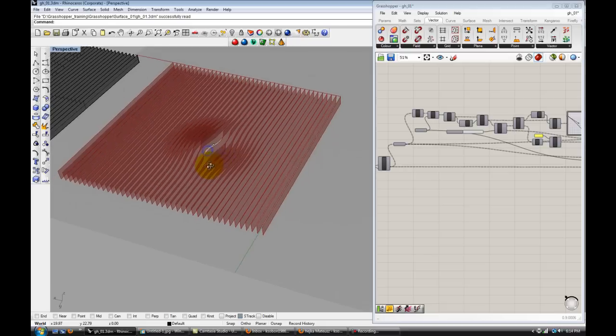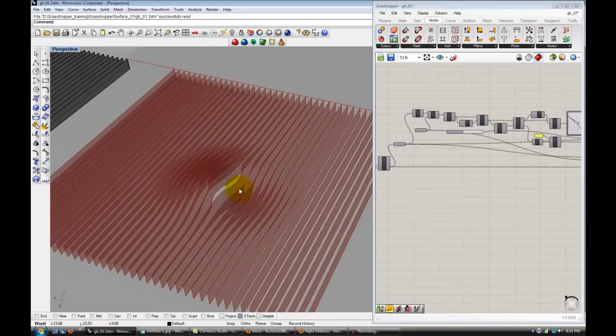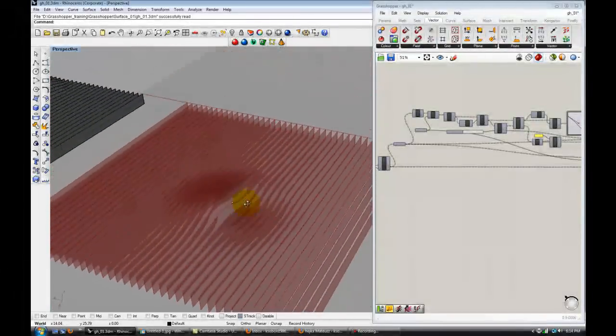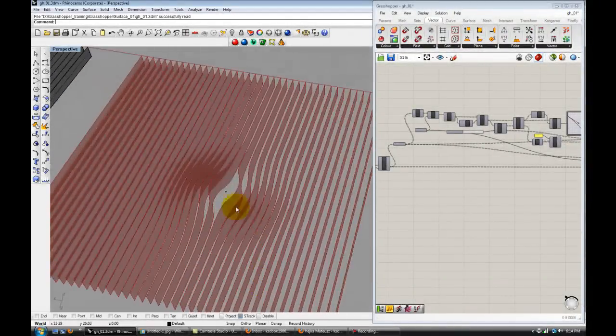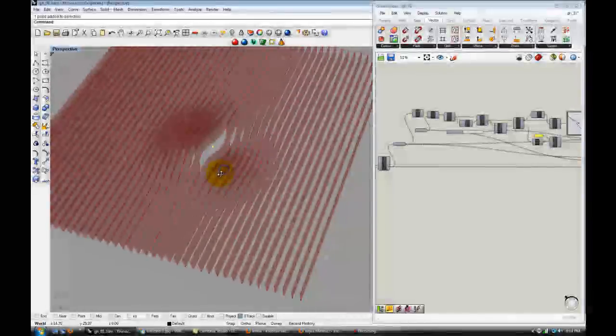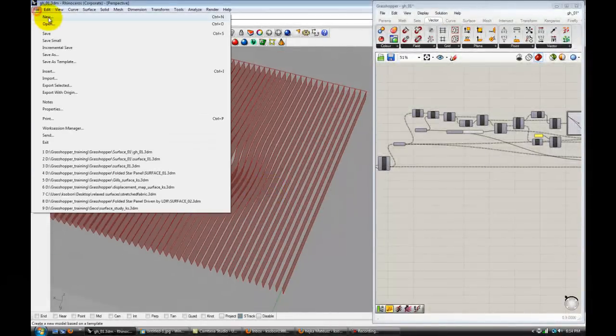The objective of this tutorial is to create geometry of fins that split open to create a clear view, and they also extrude vertically, so they create a little bit more shading wherever they split open. It's all being driven by that point, and based on the location of that point, there is a field of influence of where that geometry distortion happens. Okay, let's get started.